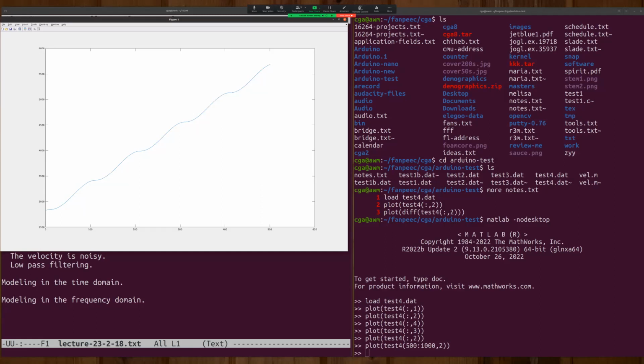An encoder is typically a disk with lines on it and some sort of photodiode looking at the lines. Every time the line crosses, it gets dark. And when the line moves out of view of the photodiode, it gets light. So what you're seeing is a square wave. And what you count is how many times you see the pulse.